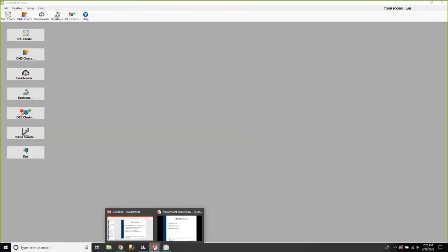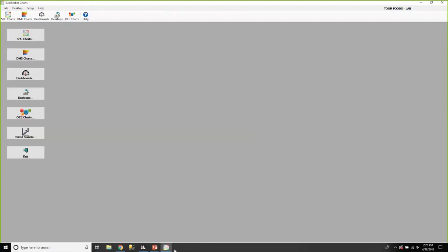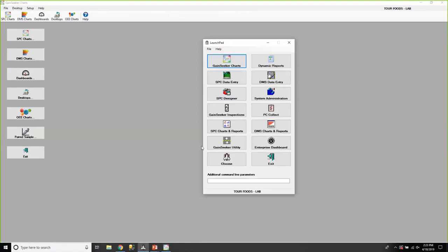So do you want to show at least some of the other items? We have a little bit of time here, so let's show another item real quick. In 9.2, we really increased the number of Python commands for the different tests on inspections. Now through Python, you can get or set almost every test property. If it can be set in the property window during inspection design, it can probably be changed through Python. That allows you to control and change behavior while an inspection's running. Along with that, you can set the focus to specific controls while an inspection is running.